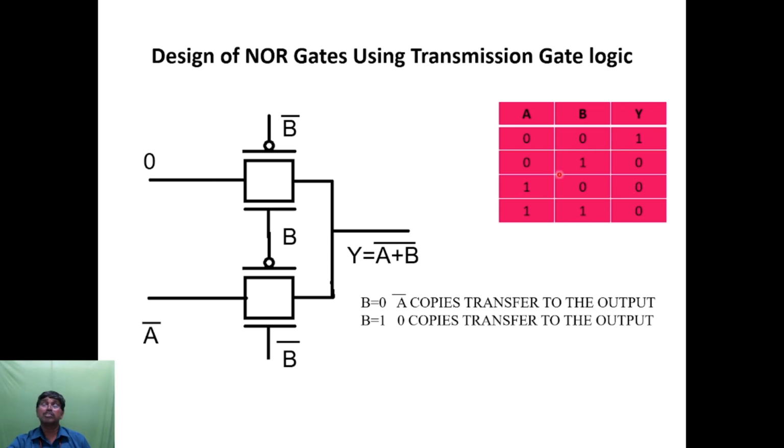That is the concept. So now I have to assign this transistor gate data input as A bar. When A is equal to 0, that means 1 will be transferred to the output. Now B is equal to 0 means both this PMOS as well as NMOS transistor will be on. Now we move on to control input is equal to 1.